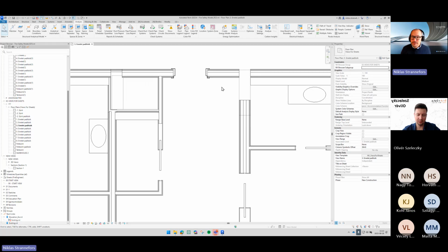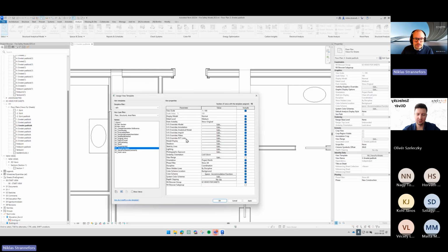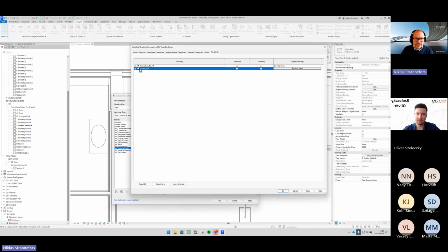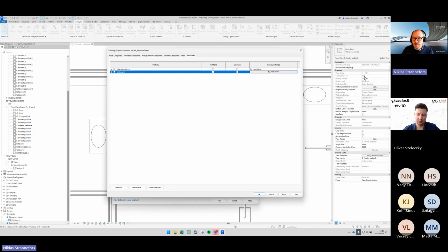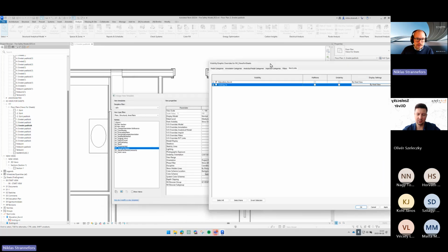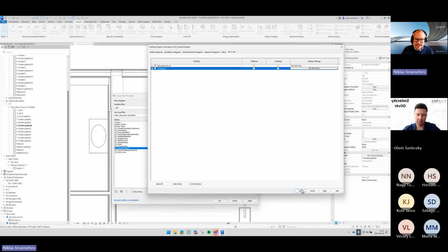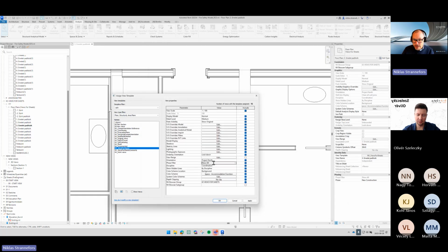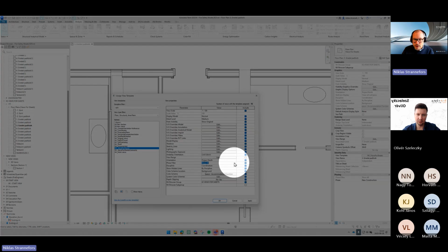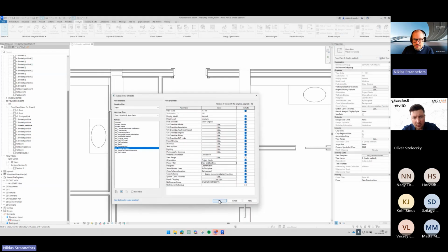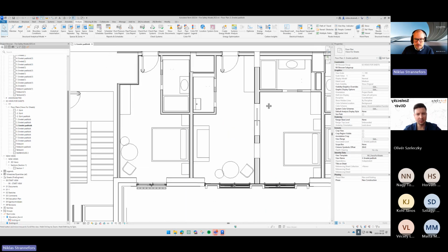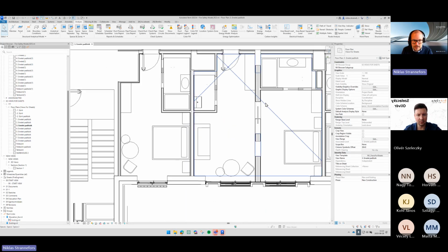Brilliant. So what I will do in this view, because we knew I'm going to fix the structure model, we can go in here to the view template and go into Revit links and turn off the existing one for now. And just go OK. So go to the view template, the view properties, view template, and view for sheets. VG override Revit links, turn off existing. And the last thing we're going to do here is change the phase filter from show all to new and existing and press OK. And now, at least in my case, it looks a bit better.